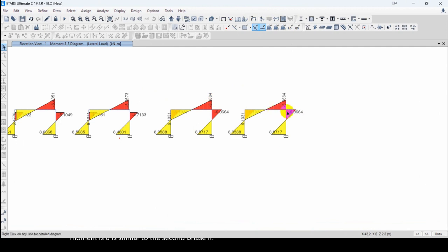It is from the center line of the beam-column assembly. These two figures represent the bending moment and shear force diagram from the center line. Whereas if we consider the in-length offset, it considers the bending moment from 150 mm away from the center line, but the values are similar. So these three values of bending moment for the beams are similar.